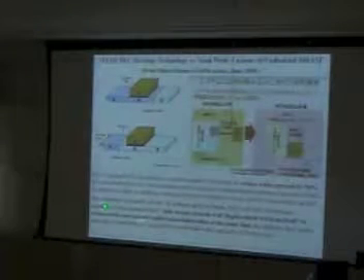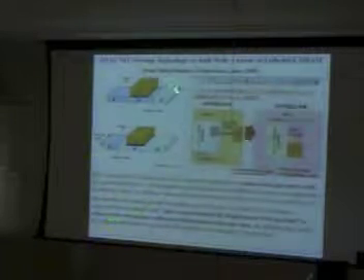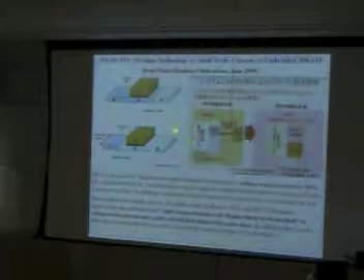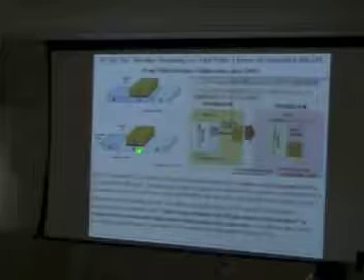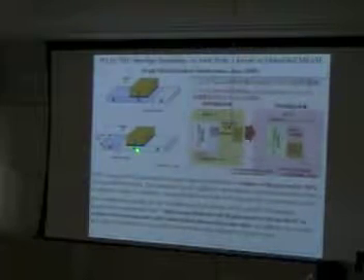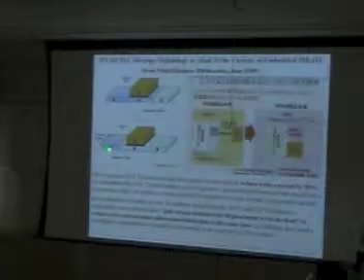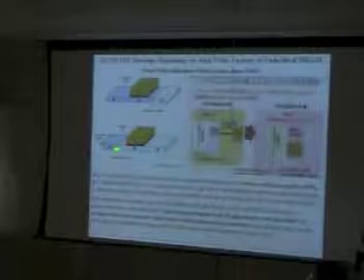There are several possibilities that you can imagine. First, this is, for example, taken from the site of the NEC company. This is an example of MRAM in which the magnetization of the bottom electrode of the magnetic tunnel junction is shifted by moving a domain wall below in this layer.